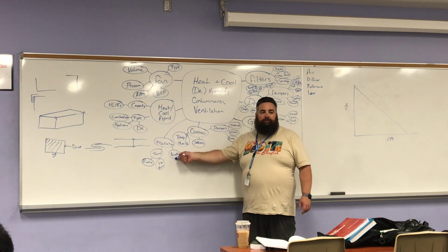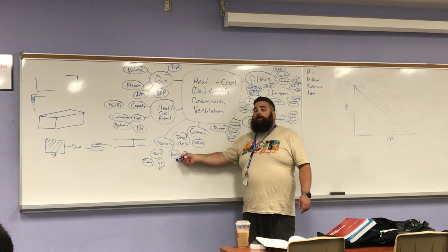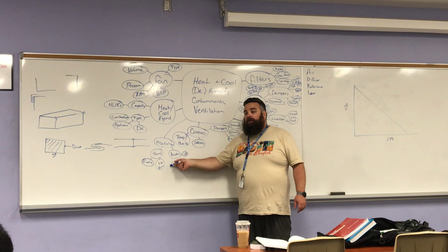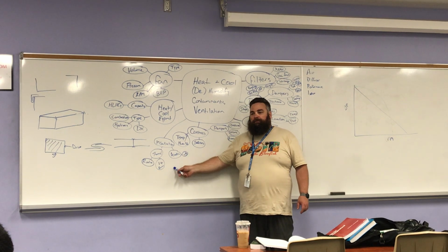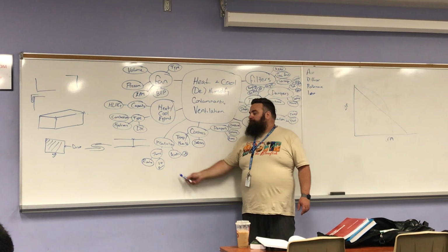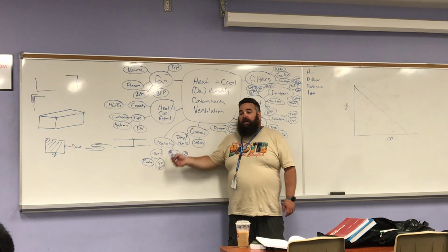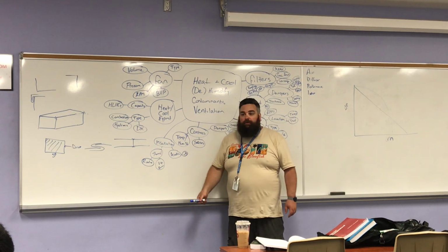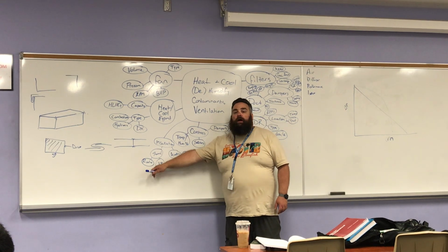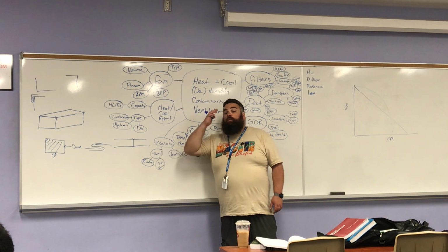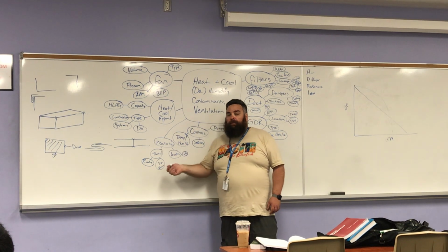We've acoustically lined everything. One, if you've acoustically lined everything, my pressure drop is way higher than design. That's not good. The other thing is, acoustic insulation is not a replacement for thermal insulation because the R value is not high enough. Even if it was, I need a vapor barrier.